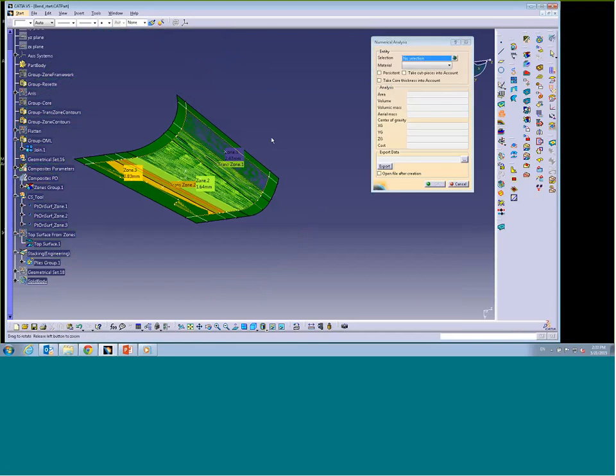Another convenient tool is numerical analysis. Let's say I want to do some mass analysis for the stacking I have. Just click apply, groups, material, all materials, and it gives me properties such as area, volume, mass, and COG, which can be exported. If I just want to get properties, cost included, for specific materials, let's say I want to know how much Kevlar I'm going to use in this model, I would select that, and you see it tells me the area and so on. So I can go with materials and go back to all.